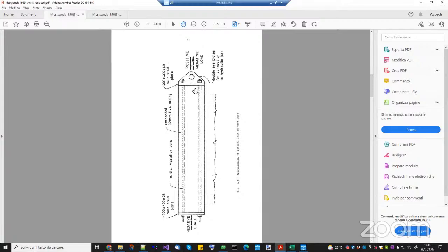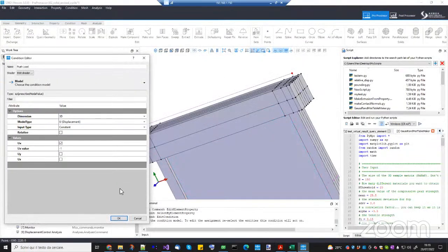And the other point, this one, and the rigid link represent these connectors, okay? So basically, when I will be pushing, the contact here will be active, and here it will be inactive. When I will pull it, here it will be in separation, so no contact. Here will be in compression, so contact will be transferred to the other side. Okay, so we run it.